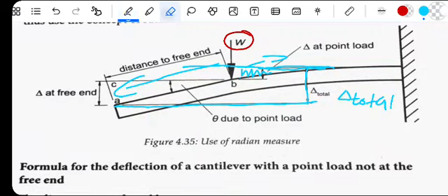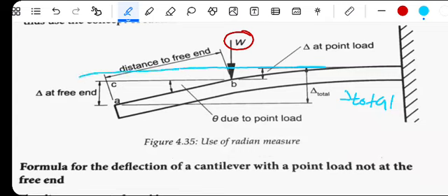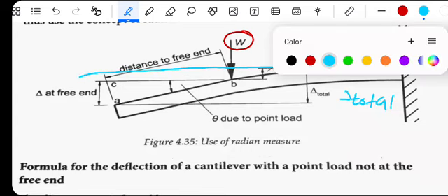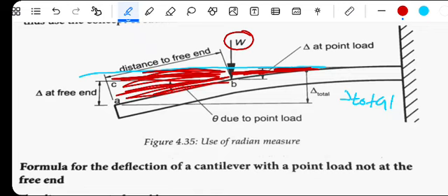So how to check the bending? If I take the horizontal line like this, you see there's a space here. It's a bending. You see, there is supposed to be no space. Also here there's a space that touches there. So there are two bendings.